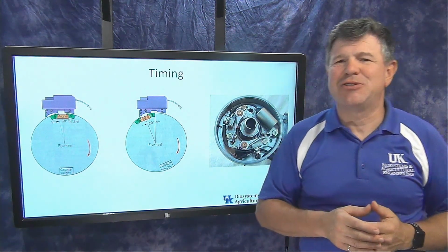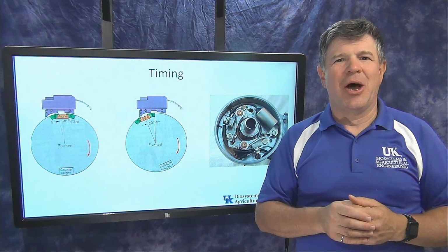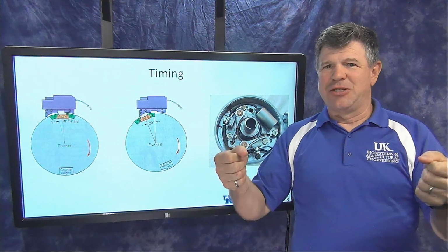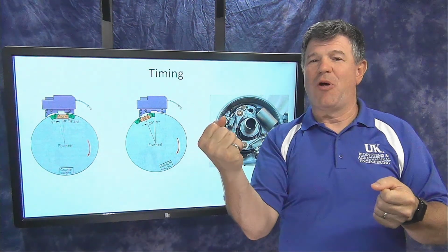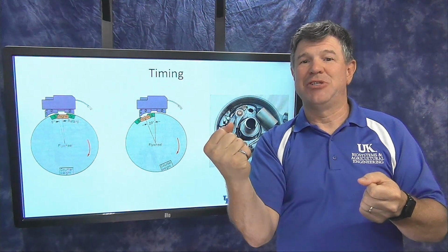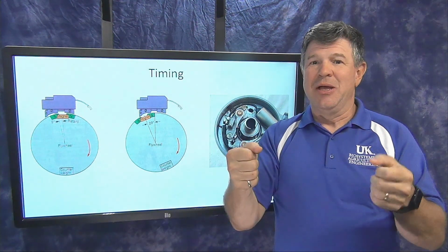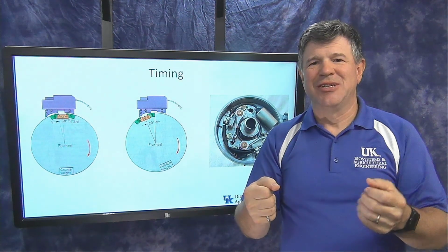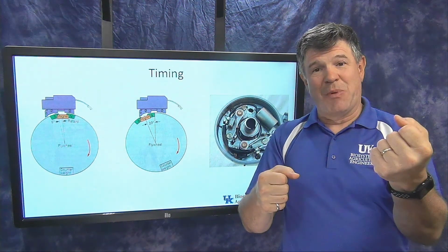Now a little bit of a history lesson. If you go back to antique vehicles, like an old Model T Ford from the 20s, you had the steering wheel, and they didn't have a gas pedal on the floor. They had a throttle behind the steering wheel, so you would pull the throttle, and that's how you would change the speed. But they had another lever on the other side, and that was a spark advance. So as you sped the engine up, you would advance your spark as well.